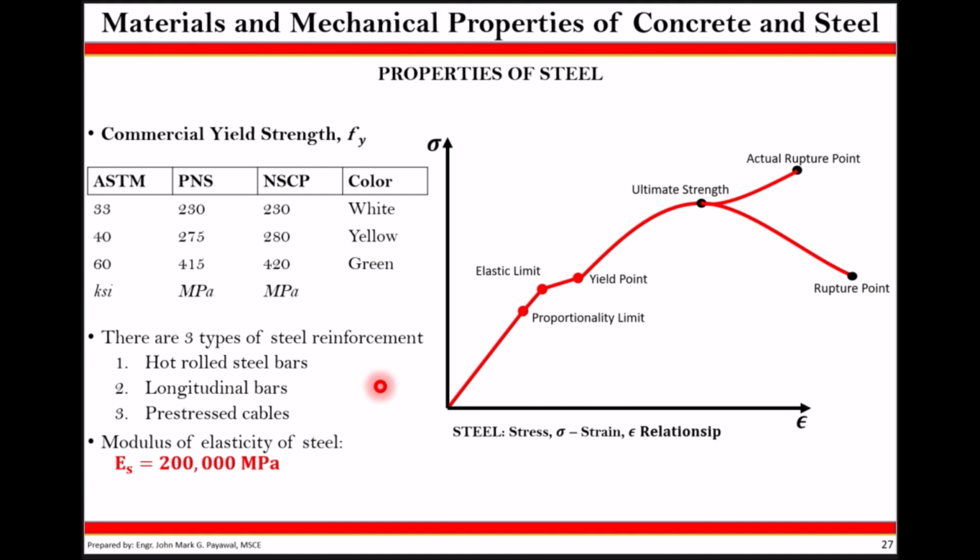It's important to relate your Es to Ec, which is termed the modular ratio, so you can convert your area of steel to an equivalent of the concrete to make it homogeneous. And when it's homogeneous, it acts as one, and therefore it becomes a better analysis and determination of the properties of your reinforced concrete design.